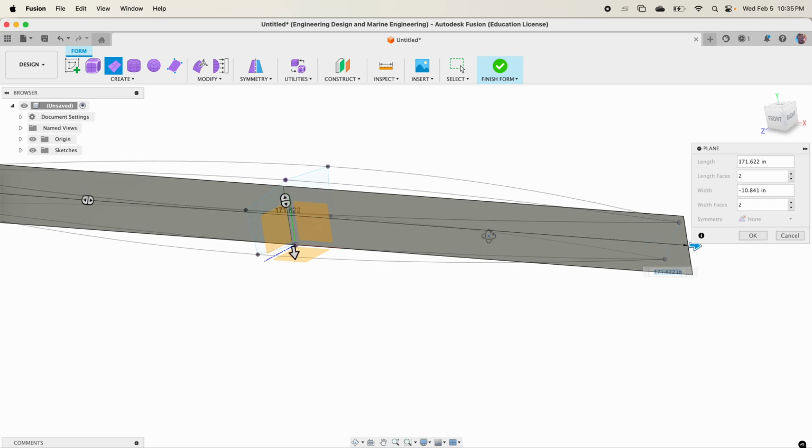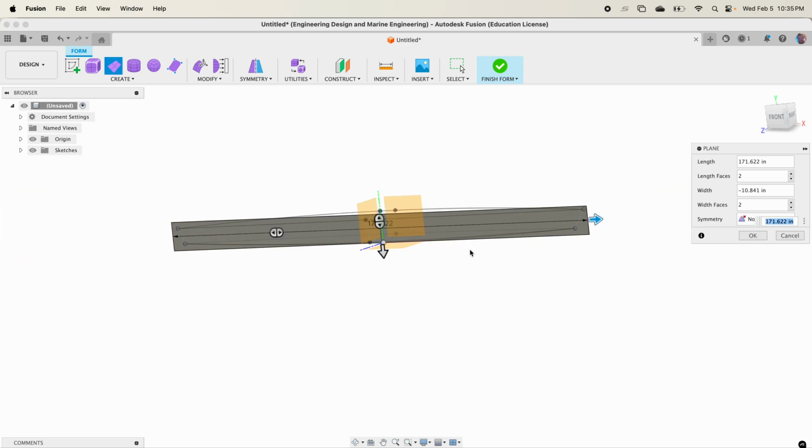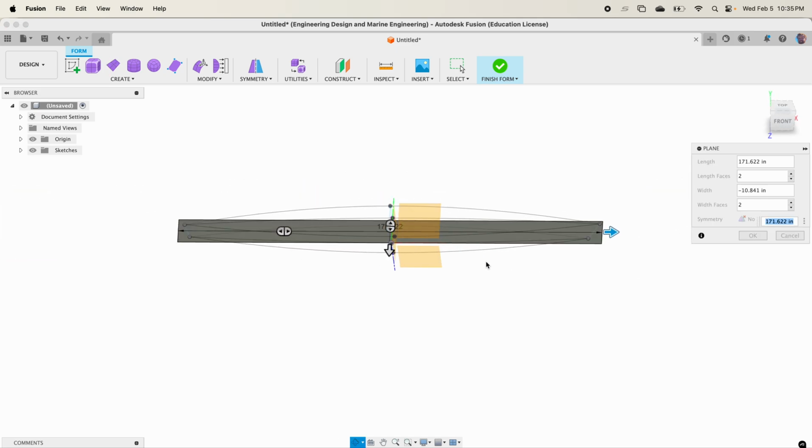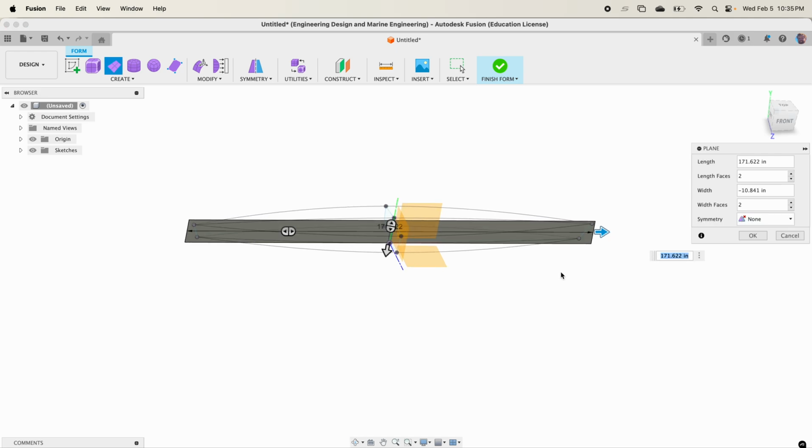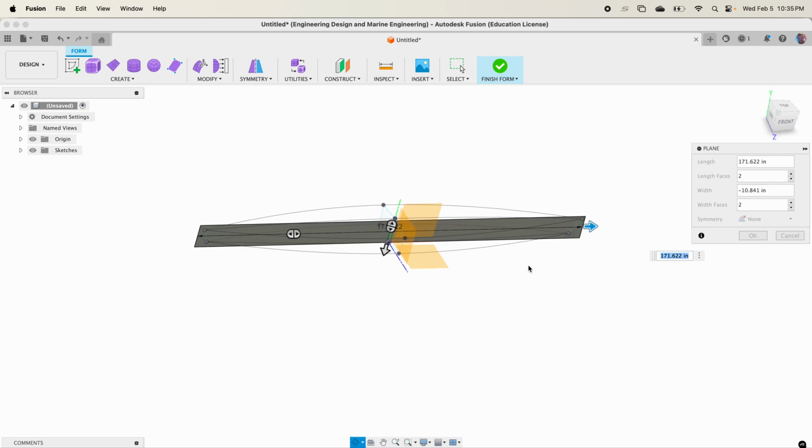Now, it's possible to make almost any shape, but we have to limit the type of shape that we make so that it will be possible to turn it into plywood later. If you imagine a plywood sheet sitting on the table or a sheet of paper sitting on the table, you can't bulge out the middle of the paper without forming crinkles or wrinkles. The same goes for plywood. You cannot bend it in 2 dimensions at once to create a fully formed 3D shape. It only bends in one plane at a time.